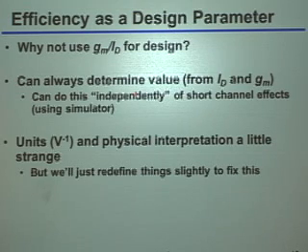Exactly. How the heck do you measure VTH? So does anybody know? How do you measure VTH? This is kind of a trick question, but go ahead. Well, you can do some interpolation tricks where you get the parabola, and I know it's not a really well-defined thing, but... No, okay, so what you said is exactly correct.